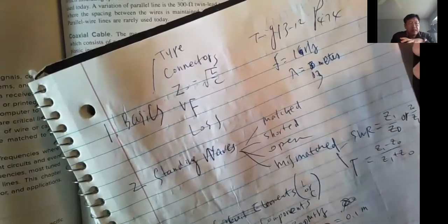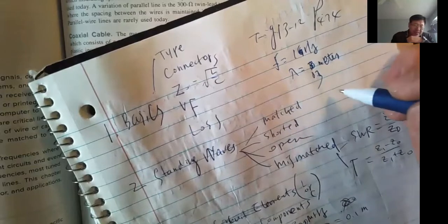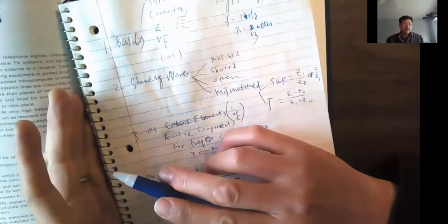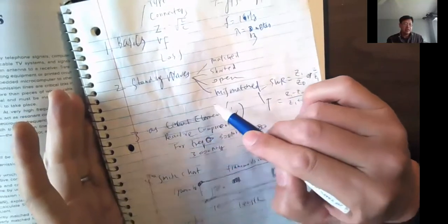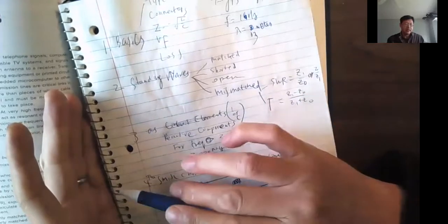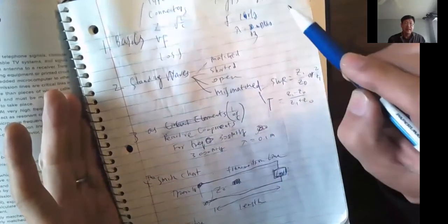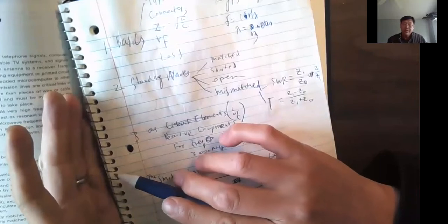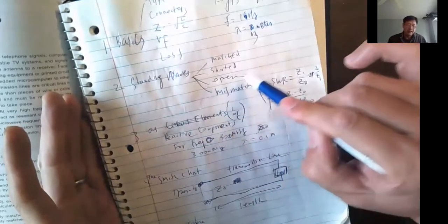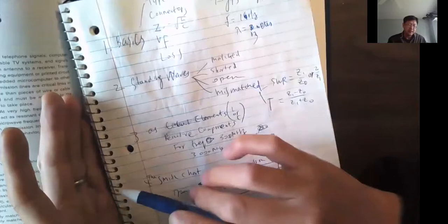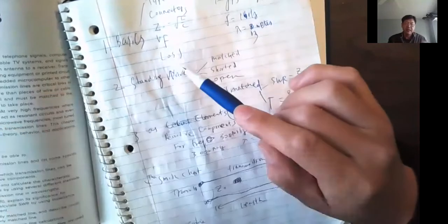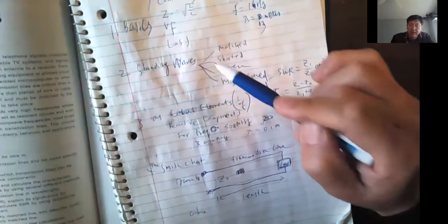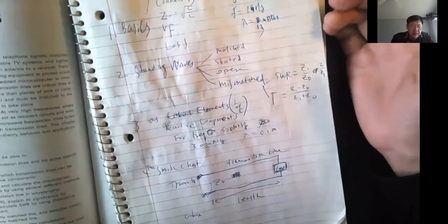That's about 1 foot. So if you think about it, that means for a wire 1 foot long, about from here to here, the voltage on this transmission line will be different. Think about it, because we are sending out, for example, a sine wave. If you can visualize, the voltage is like a sine. So if you measure the voltages at different locations, the voltages are actually different. So that's what's unique about a transmission line.